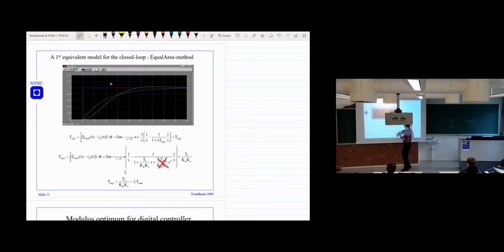This means if we have this original second order transfer function like the yellow one, and we try to approximate it, we check the area so that we can have something similar to that one, close to that one, but not exact. If we try to make the second order transfer function equivalent to a first order transfer function, that gives us a similar area, similar behavior.